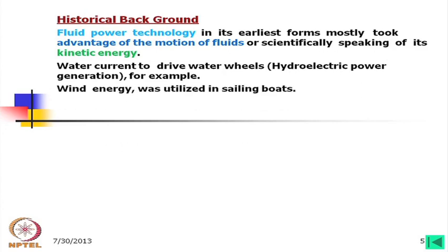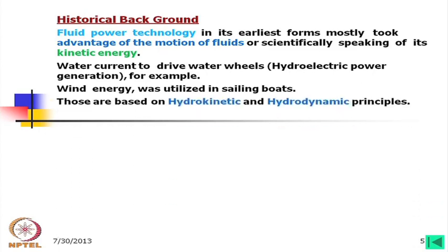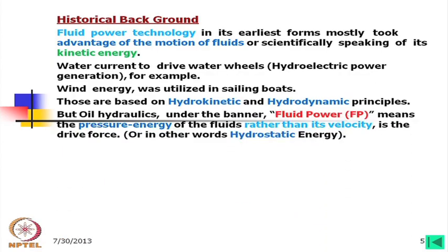Wind energy was utilized in sailing boats. Those are based on hydrokinetic and also hydrodynamic principles. But oil hydraulics, under the banner of fluid power, means the pressure energy of the fluid, rather than its velocity, is the drive force. In other words, we are using hydrostatic energy in the case of fluid power.